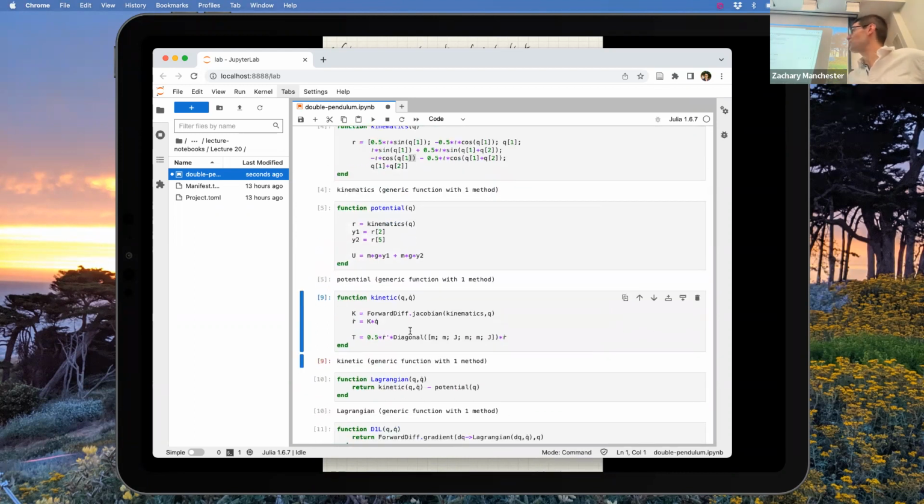We're going to do exactly what we just did. I'm going to take the kinematic Jacobian. I'm using ForwardDiff to get this because I'm lazy. But I wrote down the kinematics, I diff it with respect to q, and I get this guy. Now here's my world space, inertial frame velocity, K q dot. That gives me that vector with the r dot theta dot of all these guys.